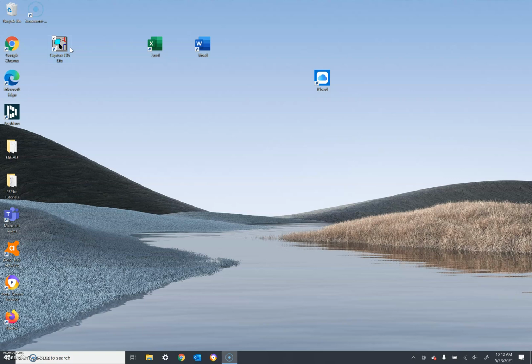If you go to the OrCAD website, you can just search on Capture CIS Lite. You do have to put some student information in, and this is a free version of the software that I'm running. So I've already got it installed on my machine. I'm running this on Windows 10. There is not a Mac version, so if you're a Mac person, you'll need to either get your hands on a PC or run Windows in a virtual environment on the Mac.